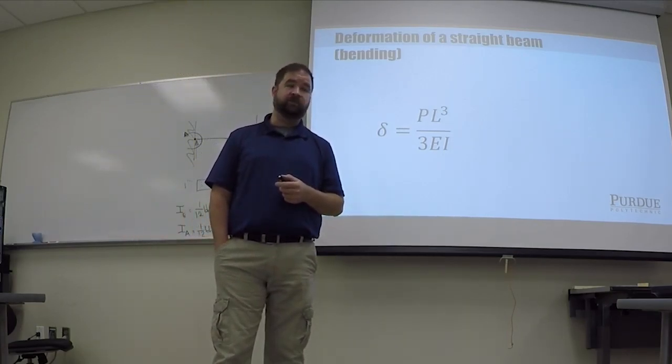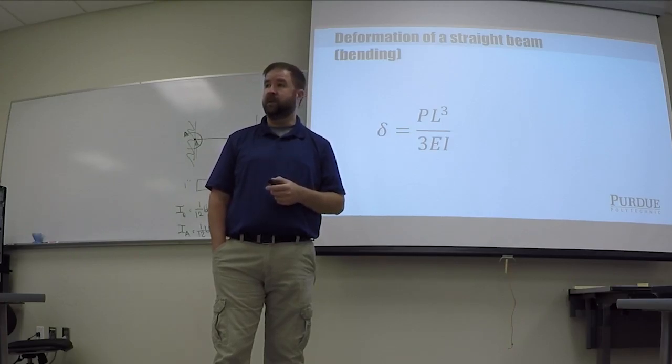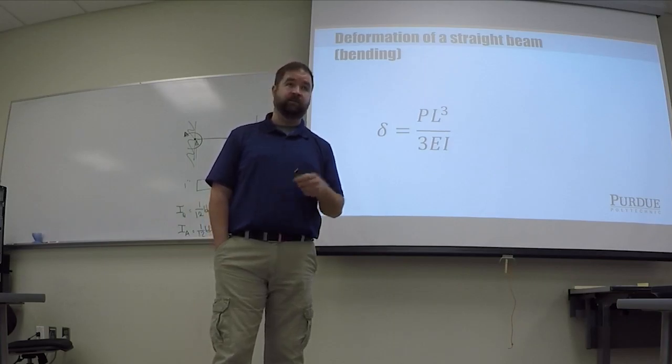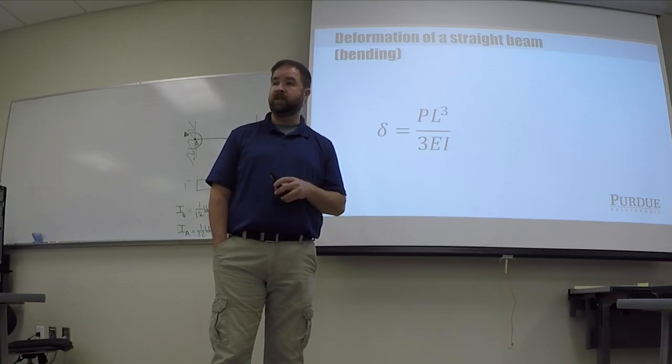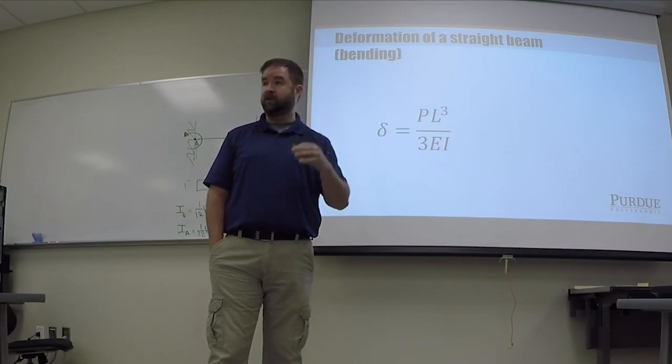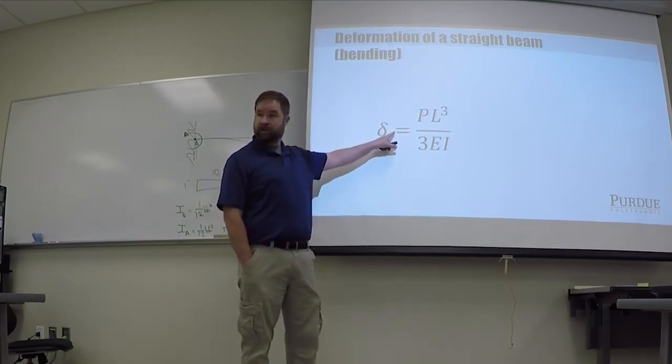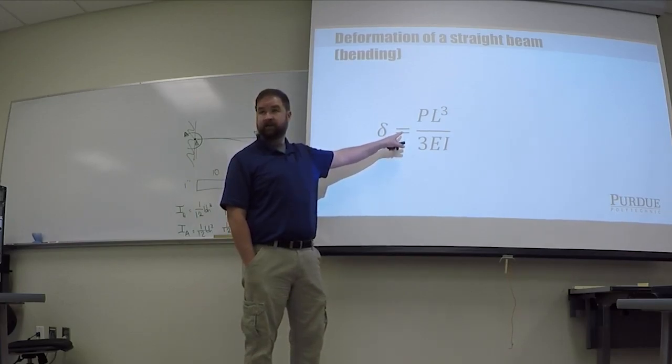If you want to buy the full version, it's expensive, but they have a free version that is very useful too. And I would highly recommend it for doing these types of calculations. If you need some help with MathCAD, I'll be happy to help you start. It's one of those things where you kind of have to learn how to do it. To do this equal sign, you have to actually use a colon instead of the equal sign.